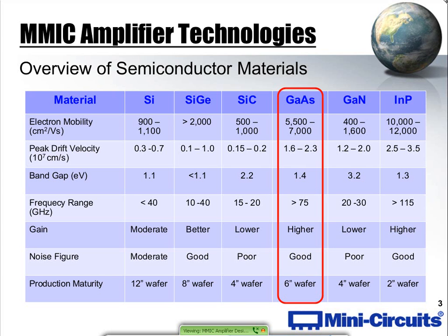The next semiconductor solution we'll talk about is silicon germanium. This has been around for also a fair number of years and is a really nice compromise between the benefits of silicon and some of the higher performance devices for higher frequencies such as gallium arsenide. Silicon germanium, there's a number of fabs that are out there today using this. Most of these are captive fabs. That means that they do not accept use by anyone on their process.